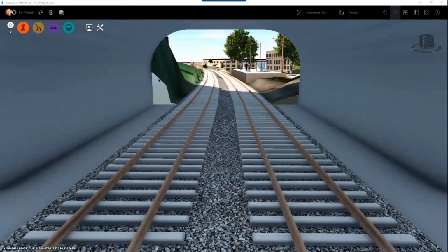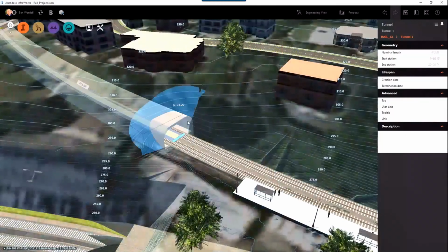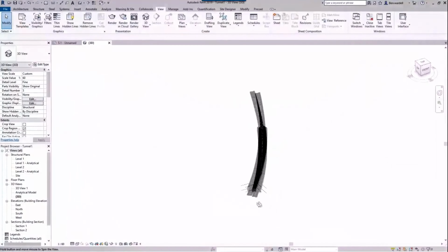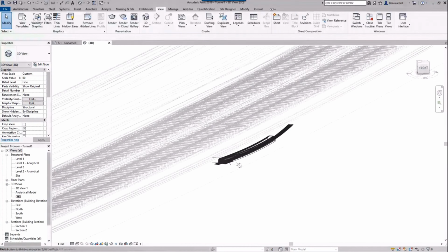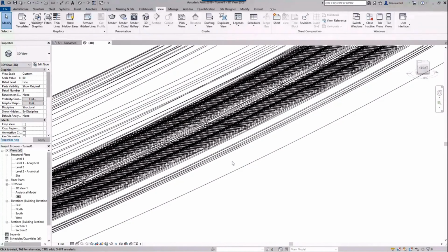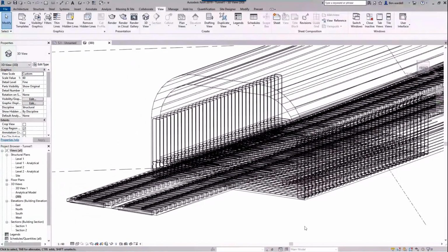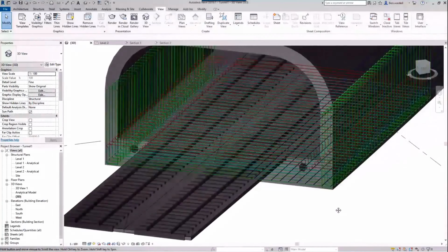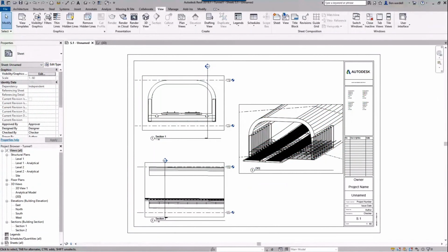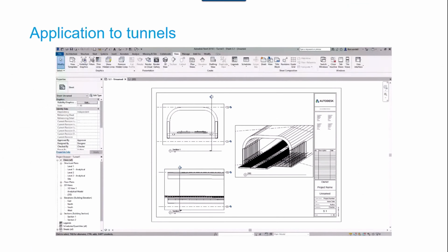The section of the tunnel can also be modified, created using Inventor. If you need some specific section for your tunnel, you have a library in InfraWorks with some default section for tunnel, and with default parameters you can do a lot of different things with the basic section in InfraWorks, but you can create also your own section with Inventor to model in InfraWorks your specific tunnel.